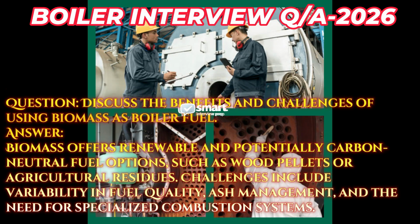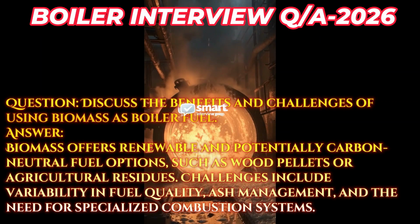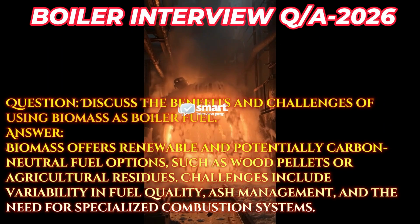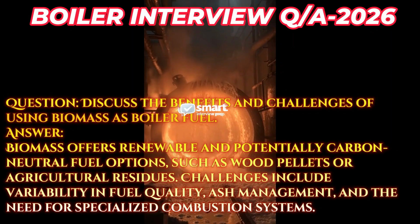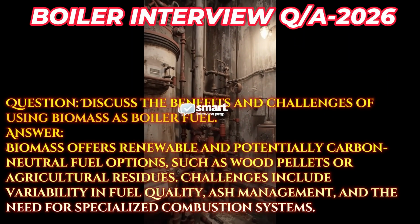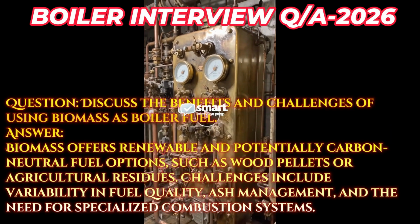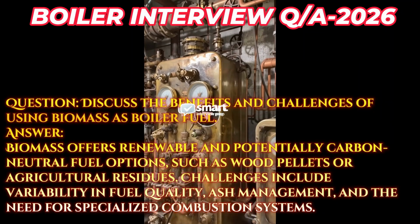Question: discuss the benefits and challenges of using biomass as boiler fuel. Answer: biomass offers renewable and potentially carbon-neutral fuel options, such as wood pellets or agricultural residues. Challenges include variability in fuel quality, ash management, and the need for specialized combustion systems.